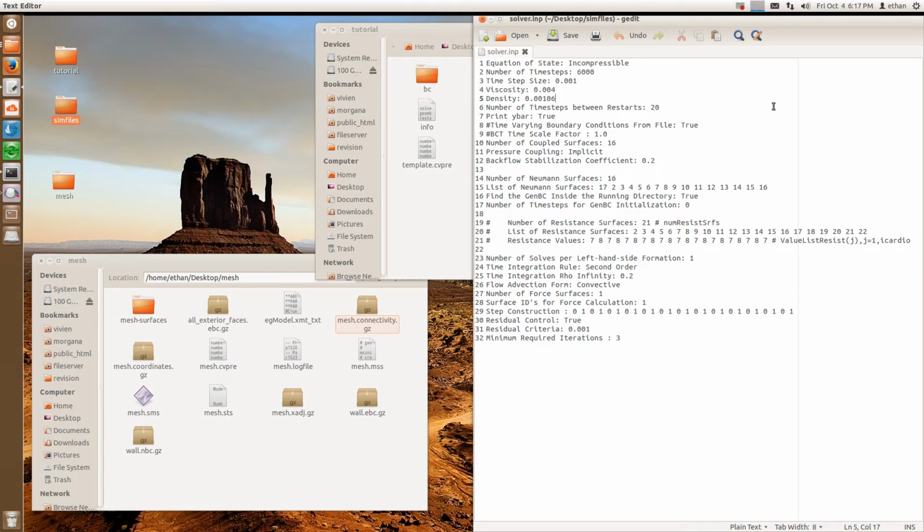You can do your own calculation to check if the values are in the correct unit system. You need to look up the unit for viscosity and for density, break it down into distance, mass, and time, and see what the right number is. But I'm just going to change it right here because I know in centimeters my viscosity is 0.04 and my density is 1.06. So they just need to be consistent with whatever unit system you're using.